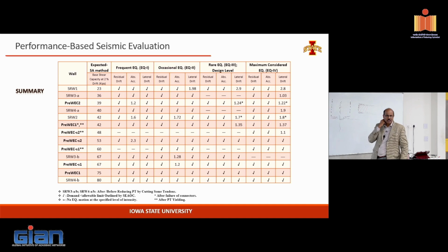I don't think we completely eliminated it, but we showed that you can actually increase the anchorage, we made it longer. It's not long in the sense of big. It's increased by a centimeter or a few millimeters, basically. Adjusting the tapering angle will change whether it's going to cut in or not. So you can certainly improve it.